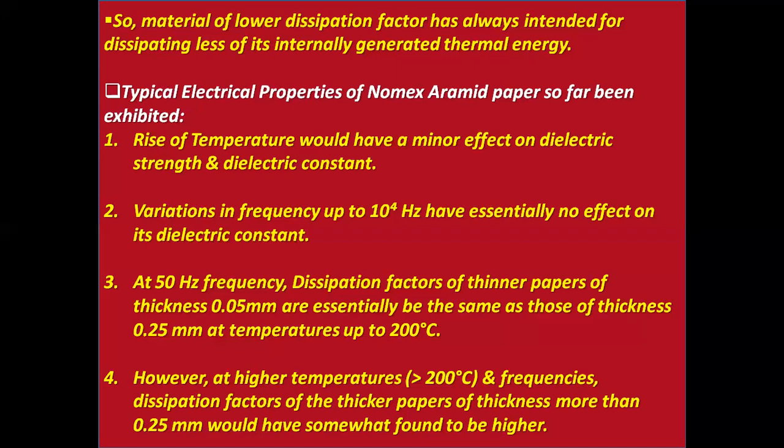At 50 Hertz frequency, dissipation factors of thinner papers of thickness 0.05 millimeter are essentially the same as those of thickness 0.25 millimeter at temperatures up to 200 degrees centigrade. However, at higher temperatures, that is more than 200 degrees centigrade, and frequencies, dissipation factors of the thicker papers of thickness more than 0.25 millimeter are somewhat higher.